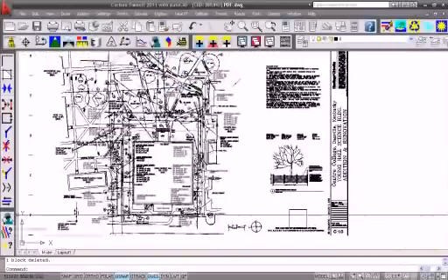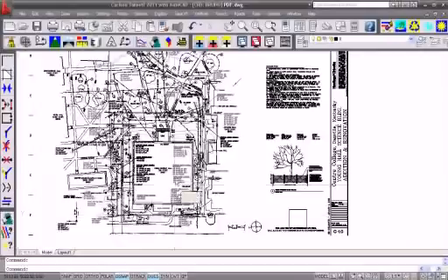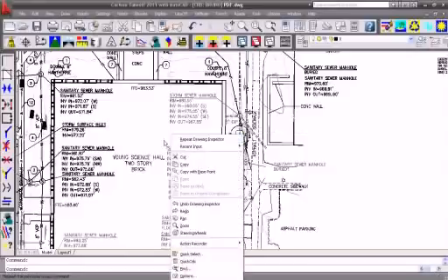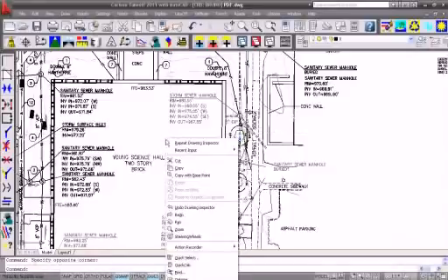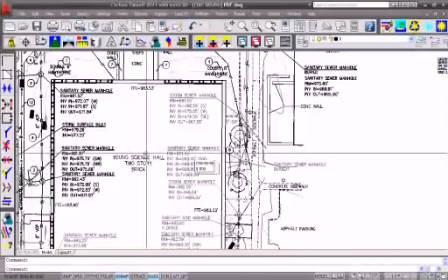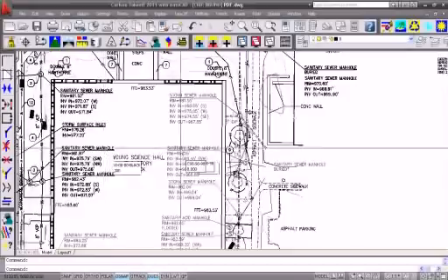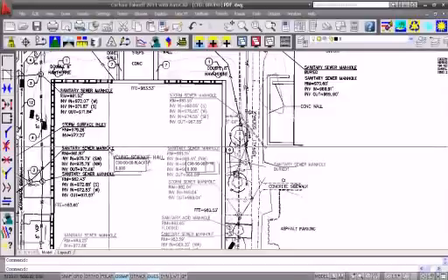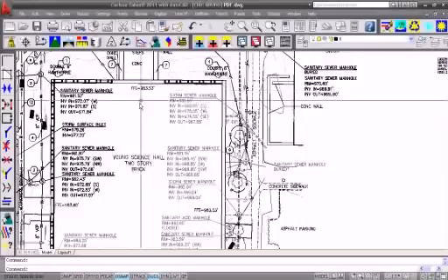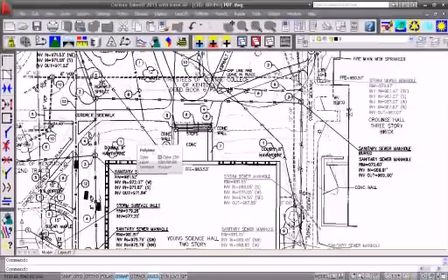And right away, I'll go to Drawing Inspector and go over this line work. And what I have checked for my Drawing Inspector is for it to show me any elevation in the line work and its layer name. And if I go over here, you can see it's set this to a layer, and this is now on a different layer, black. This is based off of the grayscale. Before, these would all be on the same layer, 0.